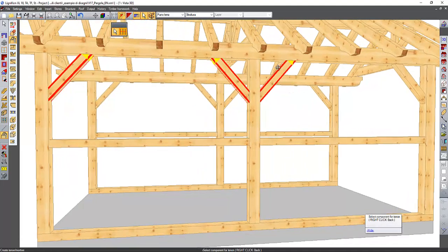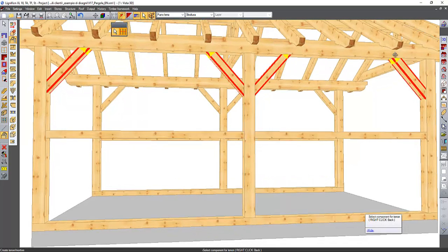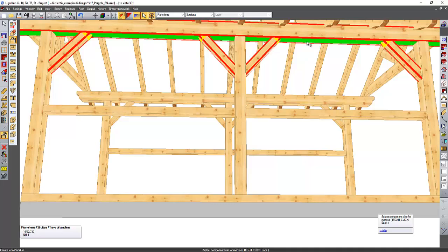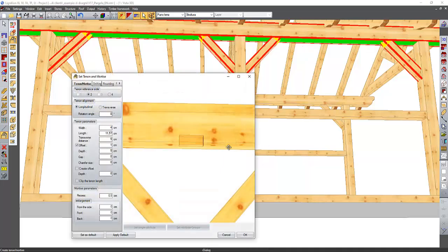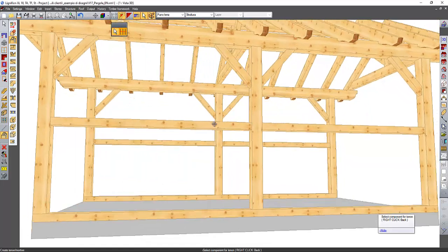We click this direction. For example, if I click here, I'm doing a tenon like this, but this is not what I want to do. I must do it here, because when I finish I click Shift, the plus disappears, and the face where we will do the tenon is this. So we confirm it, and we have the other tenon.